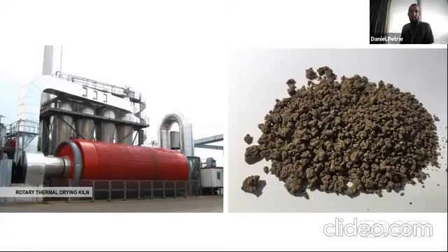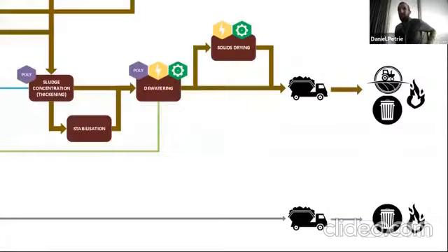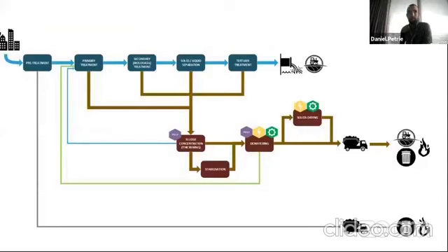But once you've got this super dry sludge, your options are still limited to putting it on land or landfilling it or incinerating it. Incineration is not something that's considered in South Africa, but in other countries where there's a high demand for space heating or industrial heating applications, they have no problems incinerating that dried sludge. So this is the whole picture.